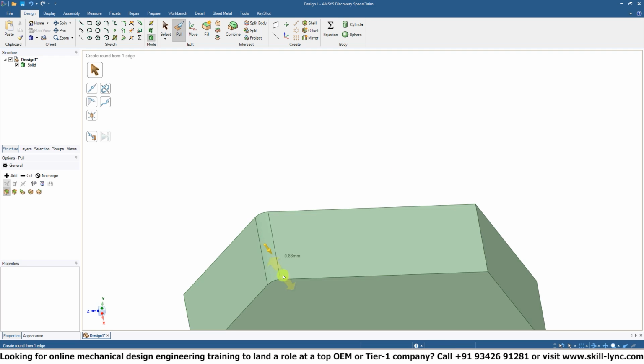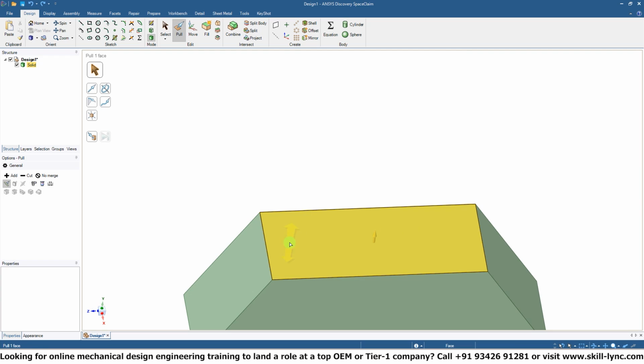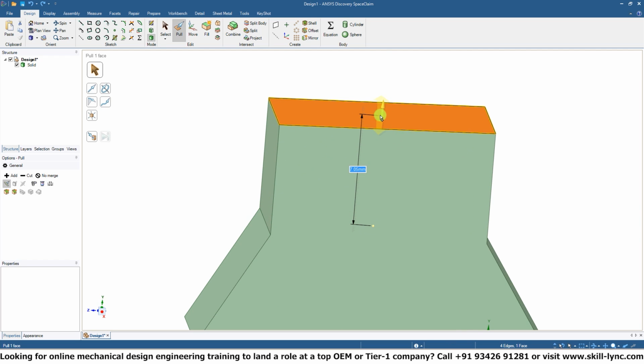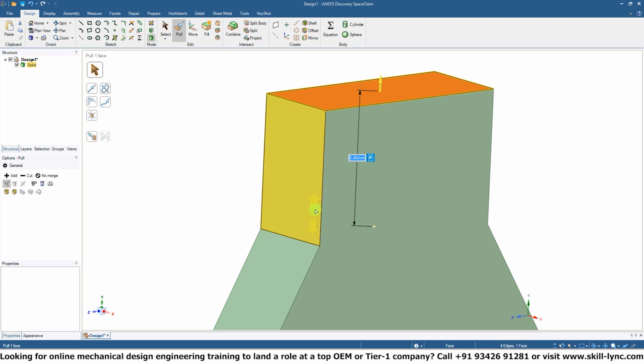Well, the same way as when you selected an edge and it turns it into a chamfer or fillet, and when you select an area, it extrudes. What happens if you select the perimeter of the rectangle and the surface itself using Control? Now, as you can see, we have the surface area selected, we have the perimeter of the rectangle selected. If we drag upwards, the autocomplete function is not enabled.